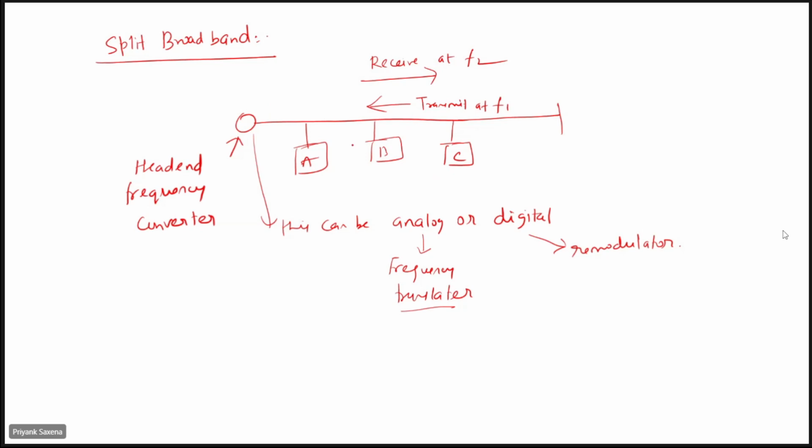This kind of arrangement is a costly one. But in a case where you have to cover a larger distance, this arrangement may be cheaper, because you have to run two parallel cables in the case of a dual cable broadband, which will be costly. So dual cable is cheaper for a smaller system, because the fixed cost of the head end is noticeable, and single cable is cheaper for a larger system where incremental cost dominates. That is the difference.